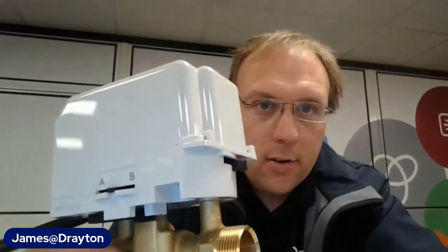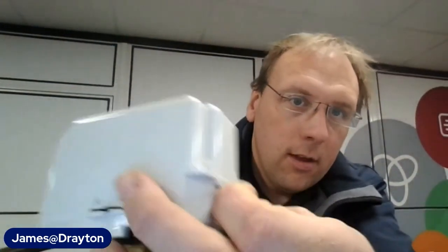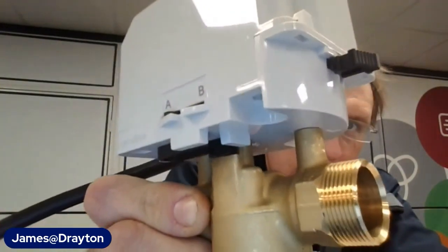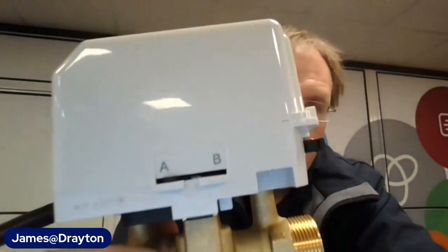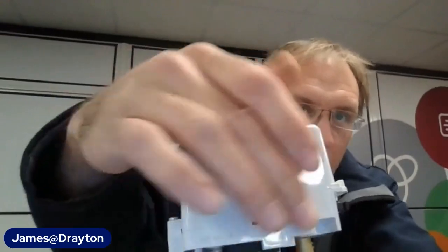Now, once you're ready to commission it, you can either move the lever over and pull it out, and you'll see that it now moves back to the A position. So under normal circumstances, that lever is hanging out of the body like that. Or if the first time you power it up, you'll move it over to position B. B is the open position, and that will unlatch this lever anyway. And then when you de-energize or you stop the call for heat for that particular zone, it will go back to the A position. So really useful to be able to see what's going on.